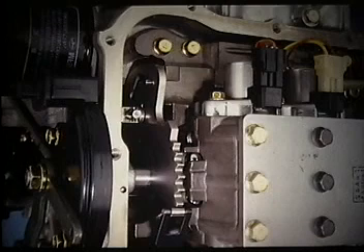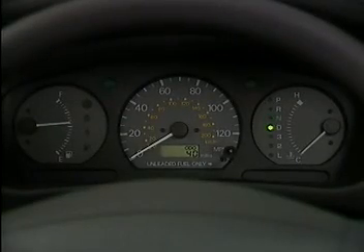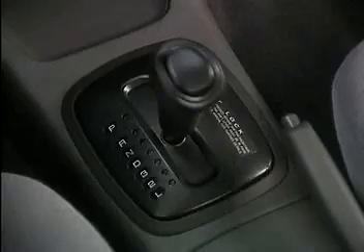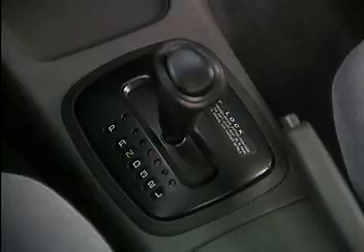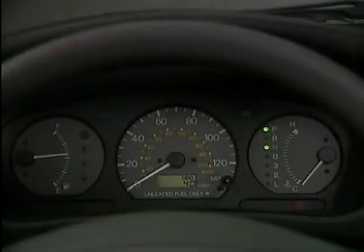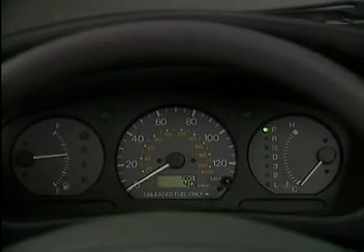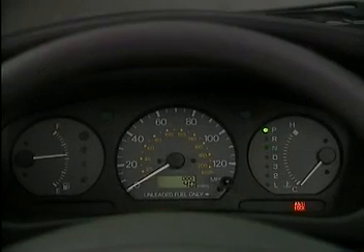A 3-position manual valve connected to the shift selector allows the driver to choose reverse, neutral, or third gear. If a malfunction causes the transaxle to go into fail-safe mode, the N-range light will flash slowly if the gear shift lever is in a drive gear. The service manual contains a list of conditions that will cause the light to flash. With the scan tool plugged in, the neutral light will flash out any diagnostic trouble codes stored. You can also observe DTCs by grounding Terminal 1 of the data link connector.